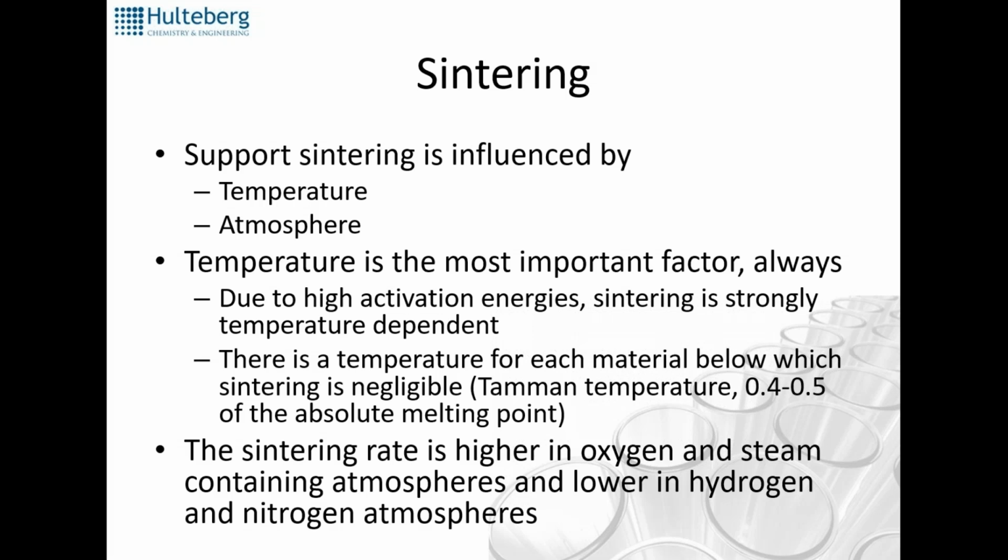Deactivation by sintering of the support requires rather high activation energies, which means that you need to increase temperature quite significantly. And there is a temperature for each material below which you can't see any substantial sintering. We call it the Tammann temperature, and it's about 40 to 50% of the absolute melting point.